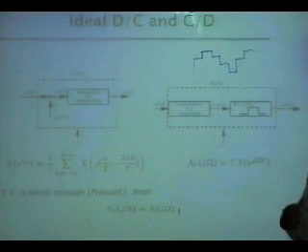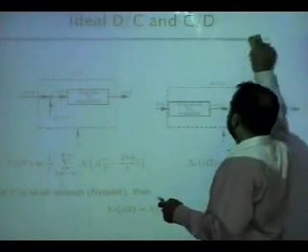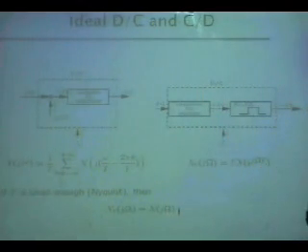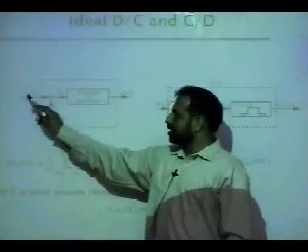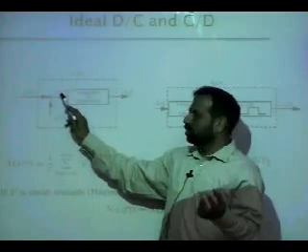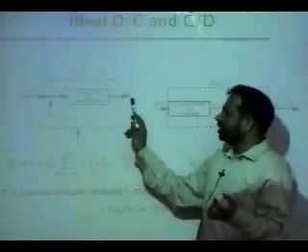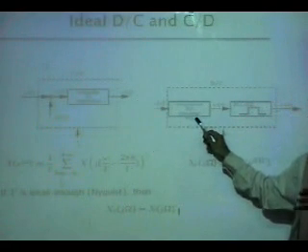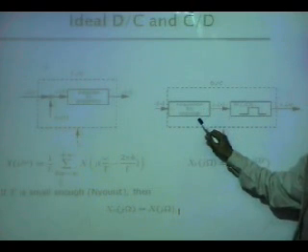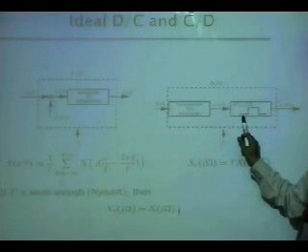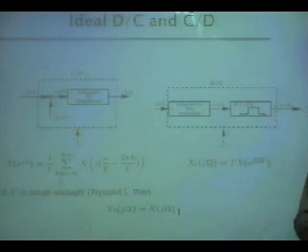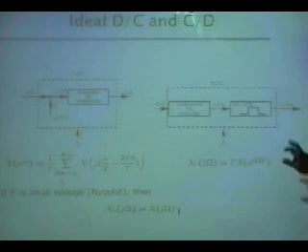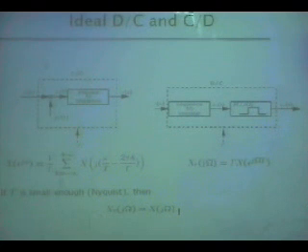Actually this is how it happens, but theoretically we have seen that by this process you can reconstruct. The mathematical model says take a signal, multiply it with a train of impulses, and you get a train of impulses. Convert the impulses to a sequence and you get a digital signal. In reconstruction you take a digital signal, bring the time back by converting the sequence to impulses, and then pass it through a reconstruction filter. Passing through a reconstruction filter in time means making copies of the sinc. That's it. It will recreate your signal. So to put the two things together, this is what we have learned.